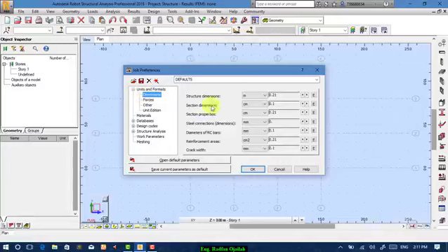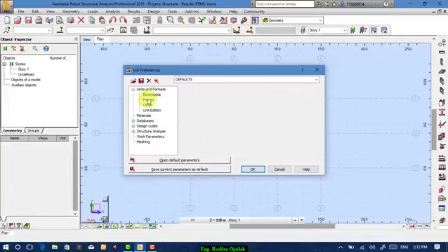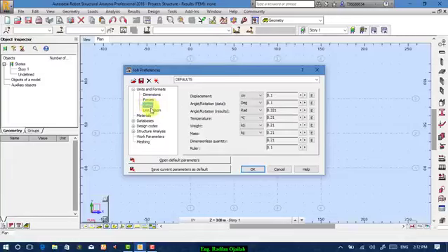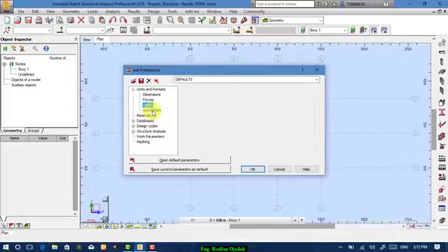And from these sub menus we have dimensions. Just set them, if you're using the metric units, set them as shown here because I have done them previously, except this one, millimeters squared, and as you wish. Okay. Forces, kilonewton meter, meganewton per meter squared, that means megapascal. These are the displacement and angles, temperature, weight. Set them as shown here.